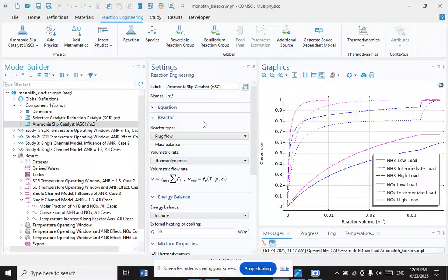The nitrogen oxides are reduced by ammonia that is injected upstream of the after treatment system consisting of catalytic monolithic reactor. The reactor has two catalyst beds with two different catalysts. The upstream bed is a selective catalyst reduction or SCR bed with the purpose of selectively converting NOx to nitrogen. The second bed is an ammonia slip catalyst or ASC. This bed should convert the remaining ammonia to nitrogen.